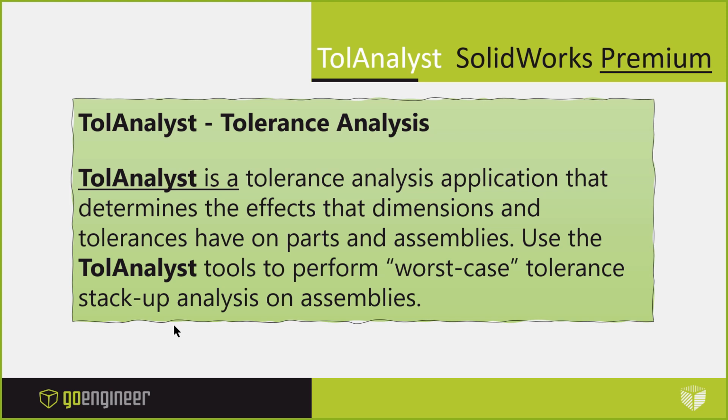So why does tolerance analysis fit into the other two topics? The other two topics are DimXpert and SOLIDWORKS MBD. The reason tolerance analysis fits into this webinar is that it uses DimXpert dimensions to do the tolerance stack up. The idea behind tolerance analysis is to give you an entry level, quick stack up of parallel tolerance stacks. Essentially, if I have parallel or perpendicular analysis that I need to do, it's a great tool to quickly run through that.